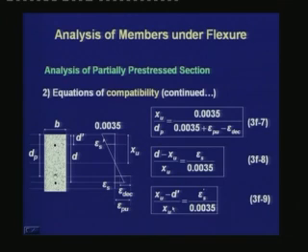And the third is the equation for the steel near the compression phase, which is xu minus d prime, the distance of the compression steel from the neutral axis, divided by xu, is equal to epsilon s prime divided by 0.0035. All these equations are from the similarity of triangles, and we see that we have got one equation for each layer of steel.